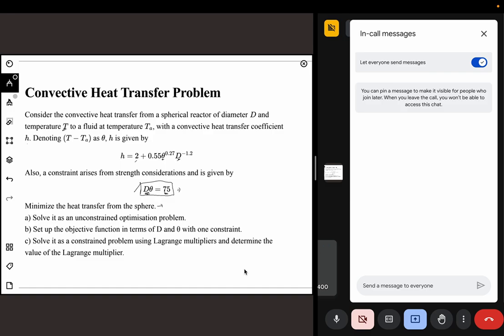The problems I usually encounter are where the functions are continuous but not differentiable. And usually calculating the gradient itself is difficult. For example, consider this scenario: you are solving a CFD problem, let's say using some ANSYS simulation. You take some velocity condition. If you're trying to simulate a room with some occupants inside, you want to decide how much velocity you have to send the air from the diffuser. The objective function is the thermal comfort of the occupants. So how do I get the derivative of that with respect to the inlet velocity?